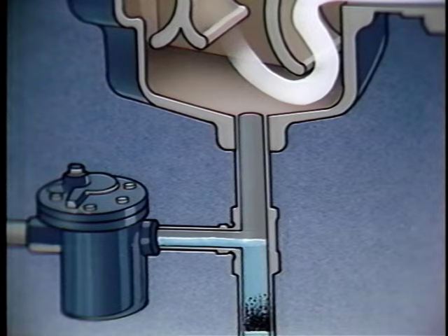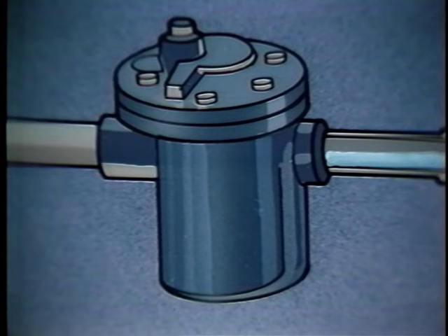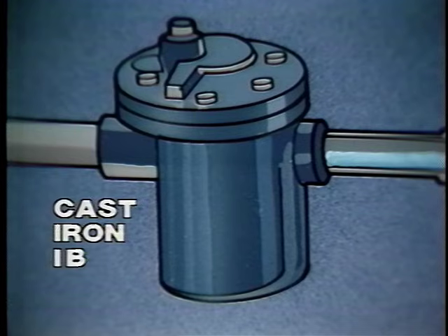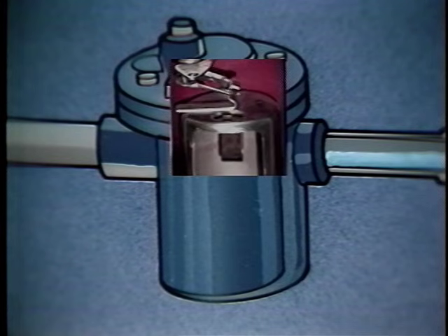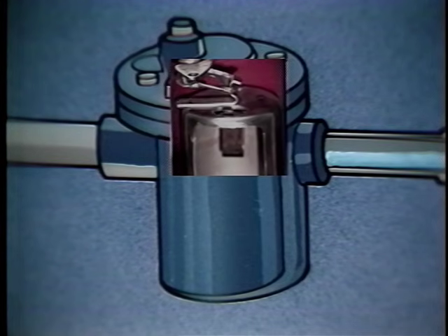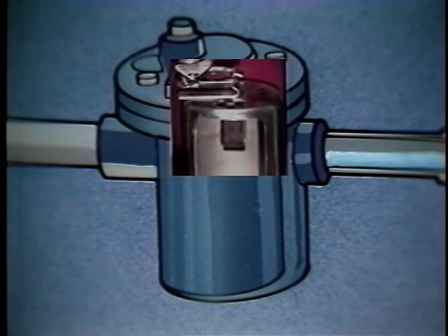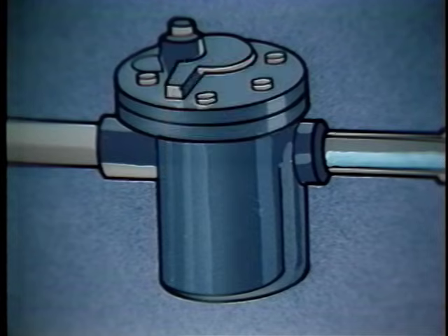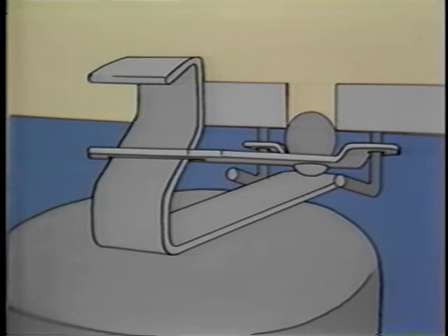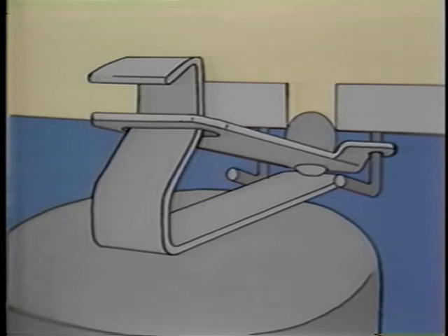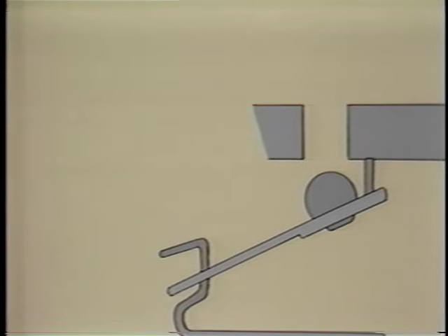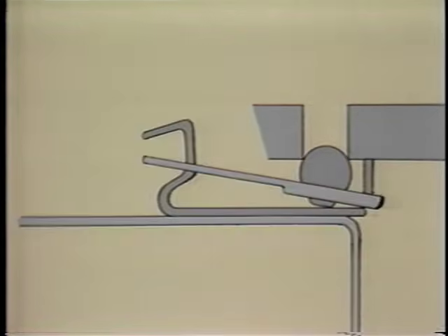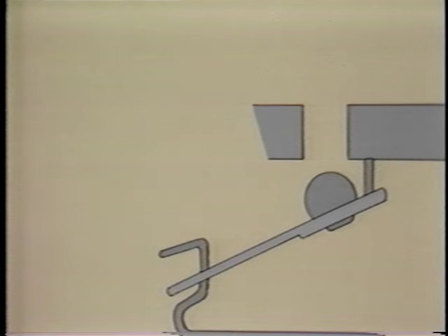Condensate is evacuated from the drain leg through an Armstrong cast iron inverted bucket steam trap. This trap was chosen for several reasons. An IB trap can handle a wide range of pressures, so resizing isn't necessary if steam requirements change. The IB trap has only two moving parts with no fixed pivots or complicated linkage. Its simplicity provides for a long service life compared to other trap types.